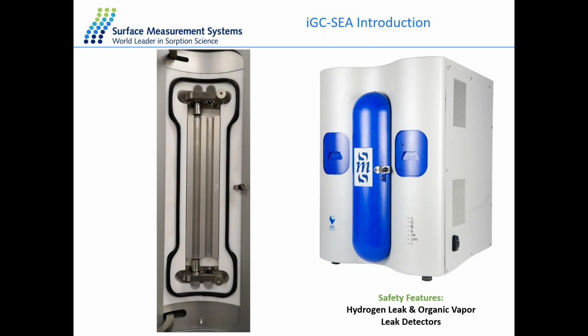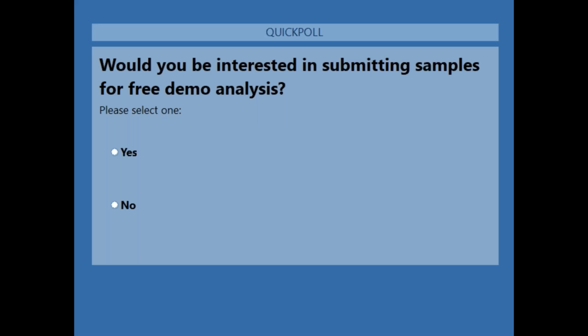Okay, there's one more question. Is the surface energy measured by IGC comparable with the contact angle technique? So yes, you can compare the two. The thing with contact angle is you're looking at specific localized areas of your sample, which may not necessarily give more realistic data, because with the IGC SEA, you're looking at the whole surface of your sample. So you're looking at your surface chemistry across the surface of your sample. However, with contact angle, you're looking at more localized places.